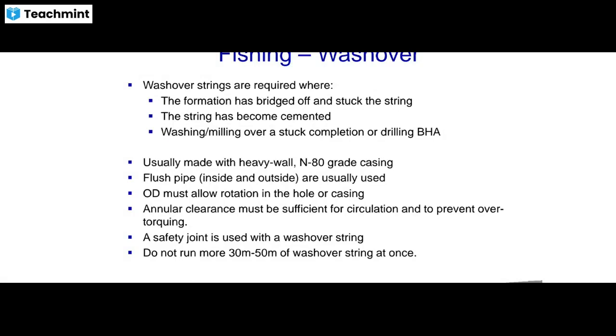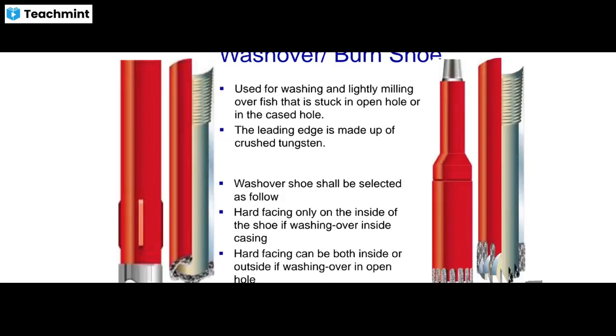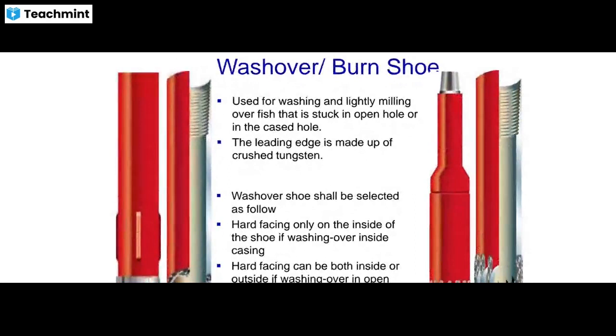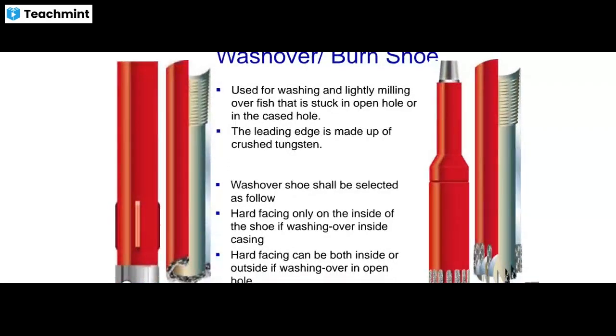So a safety joint is used with a washover string. Do not run more than 30 to 50 meters of washover string at once. So this is the washover burn shoe. You can see it used for washing and slightly milling.